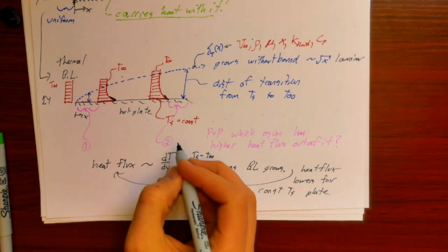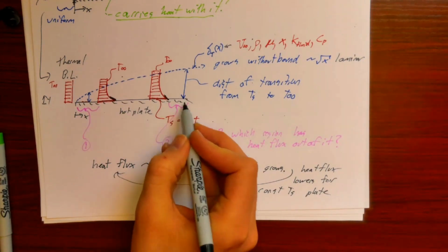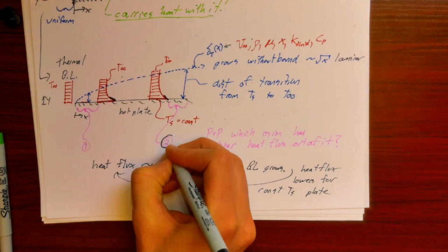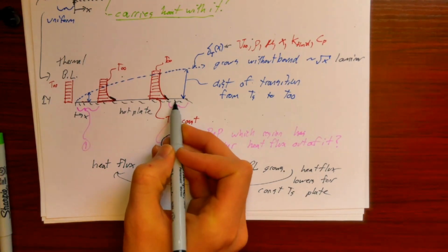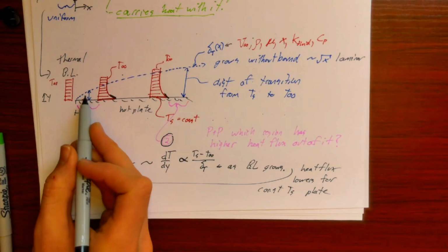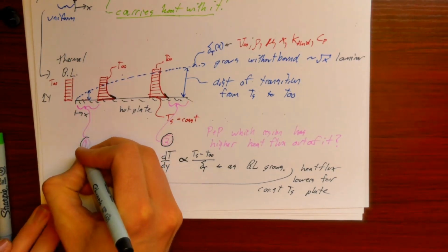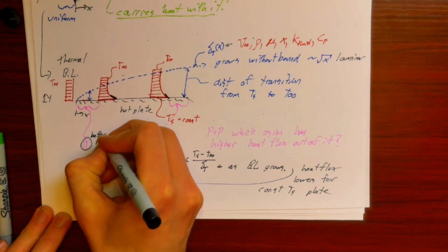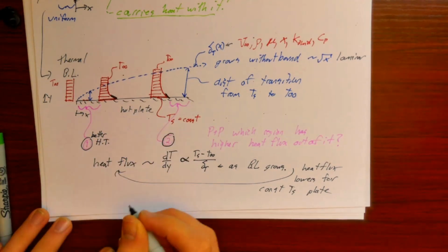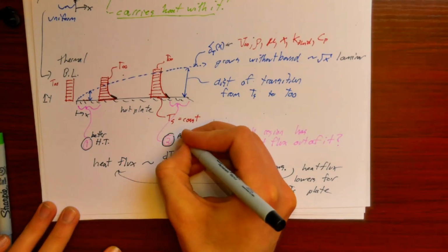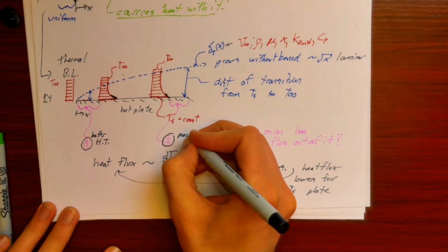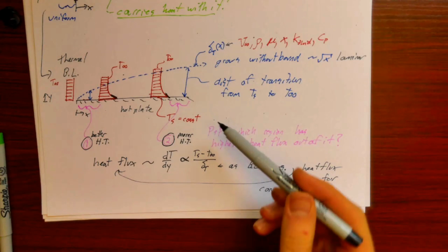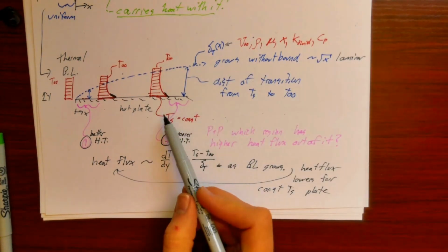That basically means this downstream region 2 is not transferring heat to the fluid as effectively as the upstream one, right? So this has better, or more rapid heat transfer, and this has poorer heat transfer. So, one rationale is basically that the thickness of this boundary layer is an explanation.